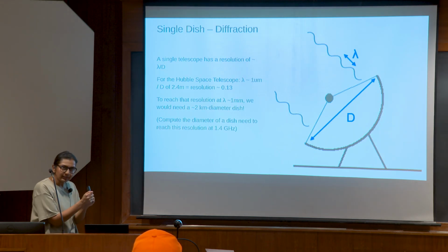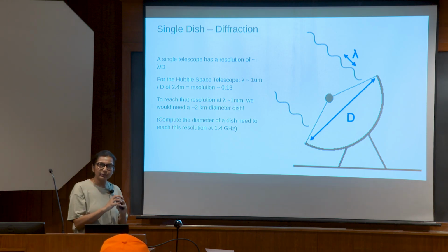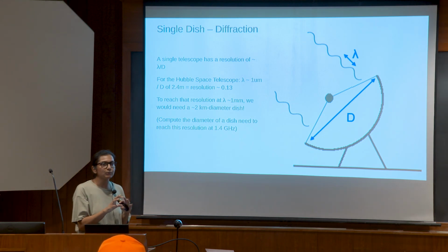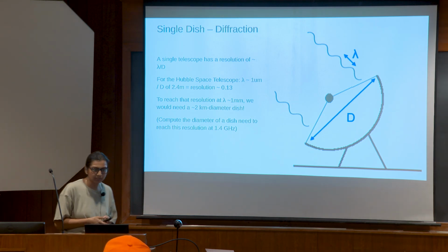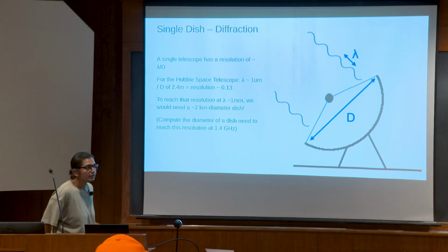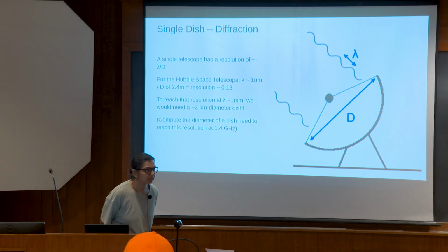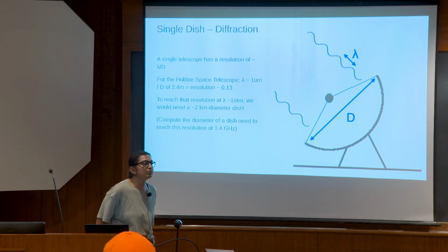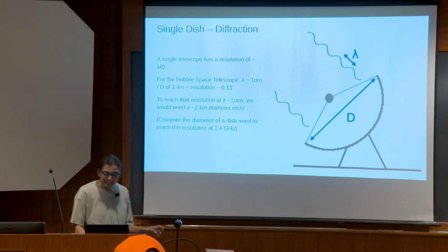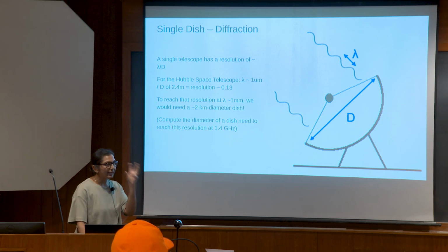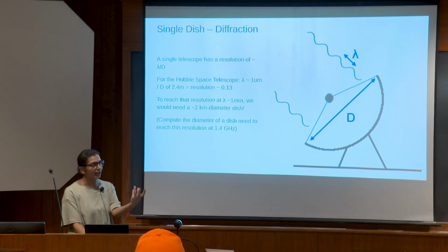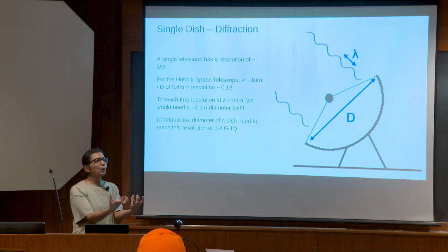So we have collected the signal, we have converted it to some voltage, and we've expressed the voltage in terms of some units of temperature. Yes. Is the Johnson noise because of the equipment we are using, or because of the signal itself? It is due to the thermal motion of electrons. So you can later equate the brightness temperature or the power you measure at your antenna to an equivalent noise temperature of a resistor.